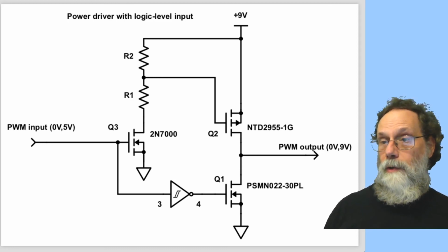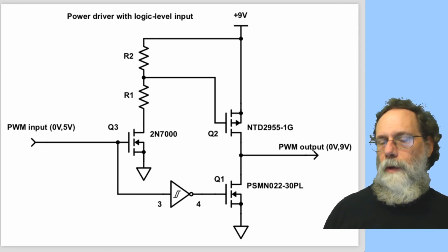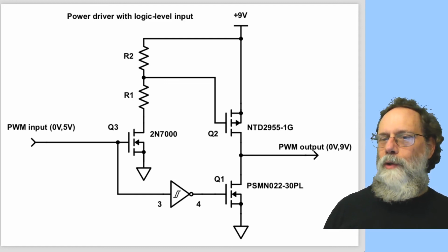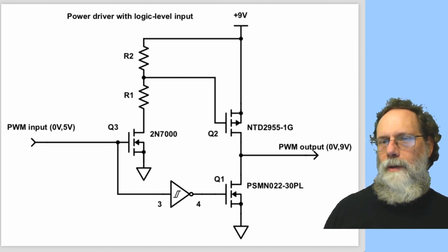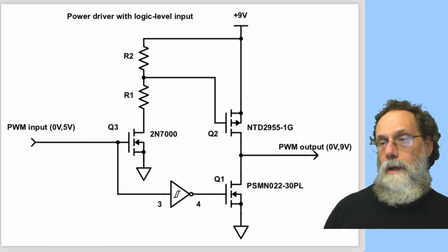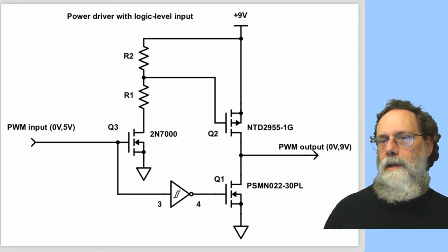And as you go to larger and larger voltages, 24 volts, 48 volts, sorts of voltages you would need for motors like wheelchair motors and stuff like that, the more important it is to get good control of the gates of Q1 and Q2. But this simple circuit would allow you to use a much larger power supply voltage than if we just did the simple designs we looked at previously, where we just used inverters to drive each of the gates.